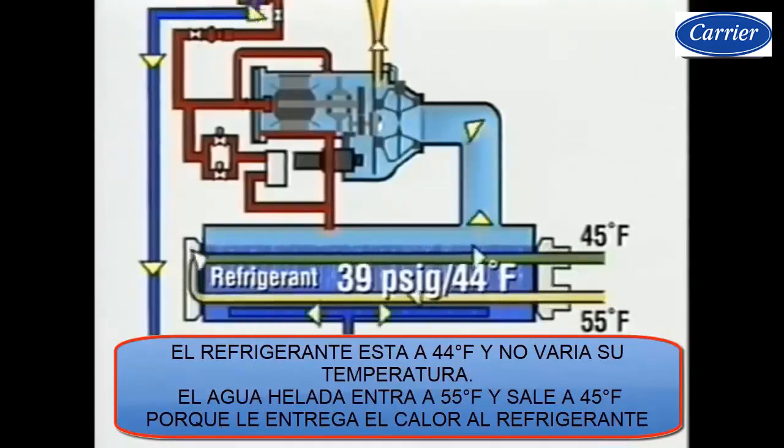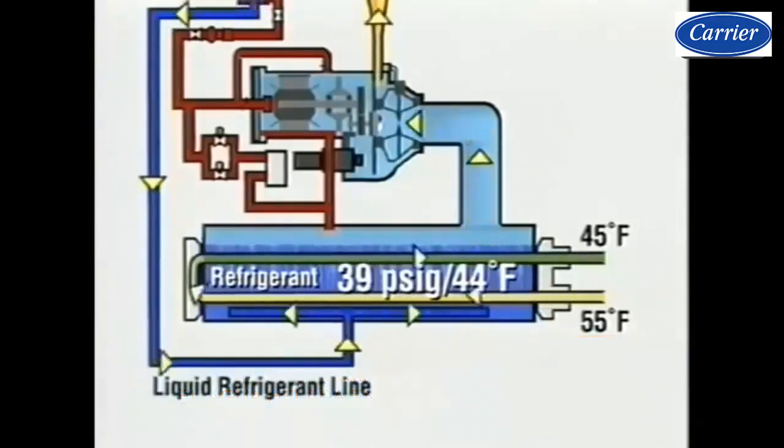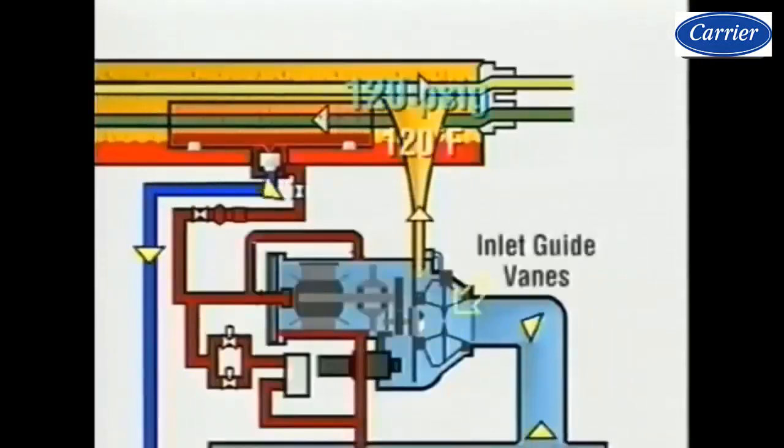We see that the refrigerant comes from the expansion. It enters the evaporator, and through the heat that is removed from the water that we are conditioning, that difference we are seeing in the water temperatures, that heat passes to the refrigerant. With that heat the refrigerant begins to boil. This process practically occurs at constant pressure, and in this way we are extracting the heat at an almost constant temperature and pressure in the refrigerant, but not in the water, because the refrigerant is in two phases. Then it can maintain its thermodynamic properties practically unaltered, while the water is in a single phase. Any gain or loss of heat will be manifested in its properties.